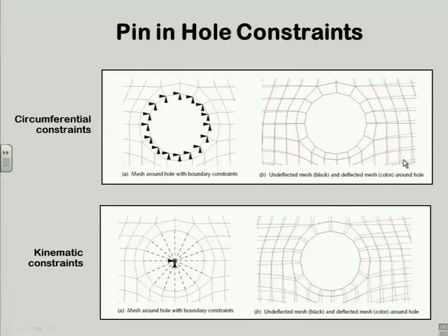And then we connect that node up with what I call bicycle spokes. So we have these bicycle spokes going out. These are elements. They're rigid body elements, so they have no deflection possible. Okay? And they're each connected to a different node around the hole. You don't see these in your model, but that's what's happening behind the curtain when you choose this particular constraint in this particular package. This is Abaqus. And SolidWorks calls it something different, doesn't talk about spokes in its description, but it's going to do the same thing.